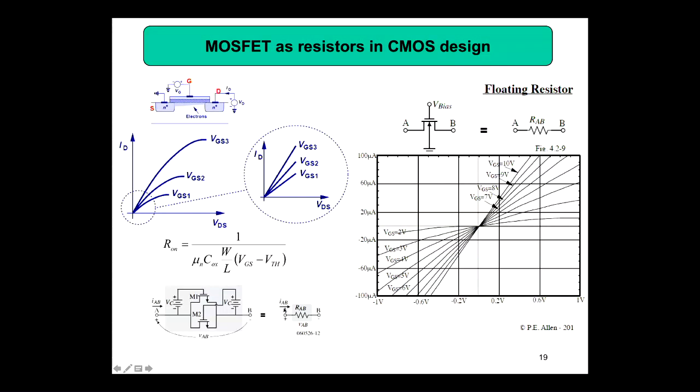Then if you want some other higher value in the chip, they will be designing something like this. They connect a voltage here, then use one MOS, then you can connect another MOS in parallel. If one MOS can't give enough tuning with this much voltage range, you can connect maybe 2 in parallel, 3 in parallel. That's what people use when they design a chip.